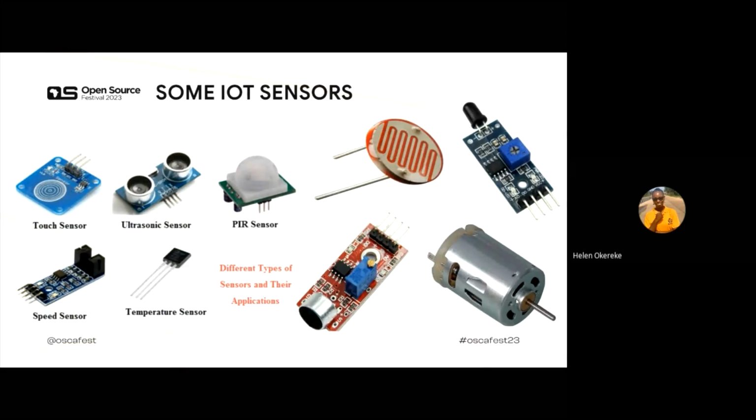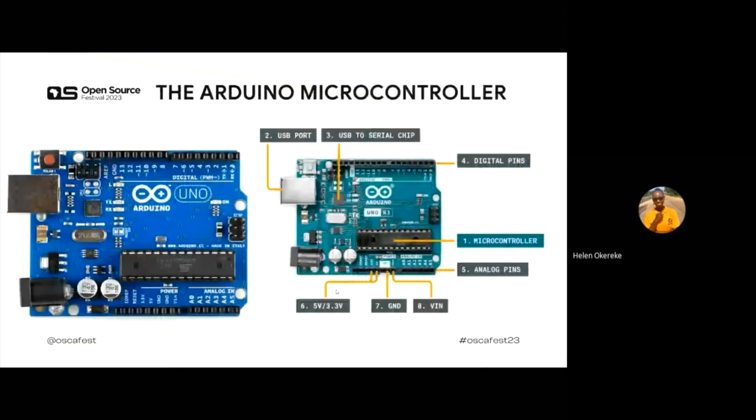So that is exactly the kind of thing that makes us use the PWM, pulse width modulation pins, for devices like the motor that are not just on and off. Remember, the motor is not an input device, it's an output device. And we need to control the stream to the motor, to know the next speed we are giving it and what speed it is at now.